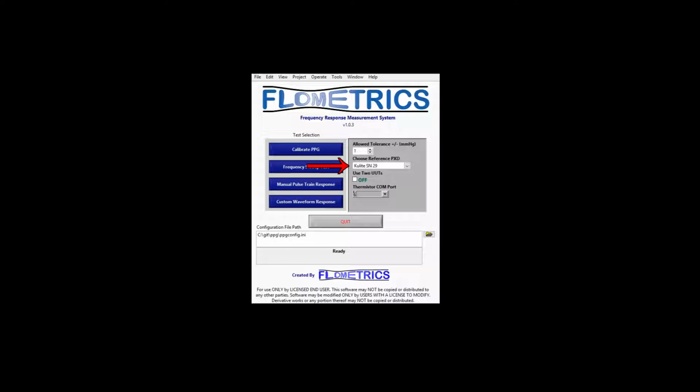Next, choose the reference pressure transducer channel. Next, check the box for Use 2 UUTs if 2 units will be used for testing. Next, select the thermistor COM port. Typically, you will only see one option here. The number of the COM port will vary based on your specific computer configuration.